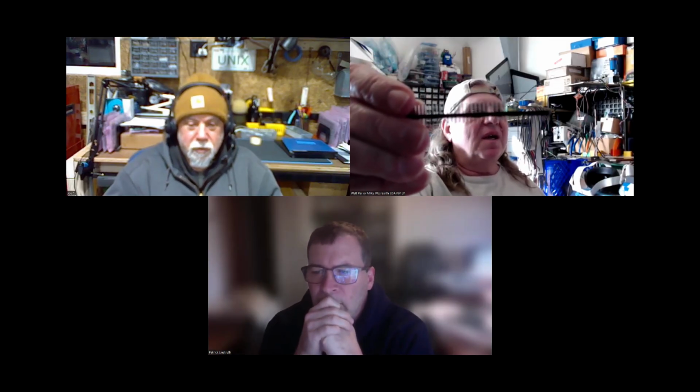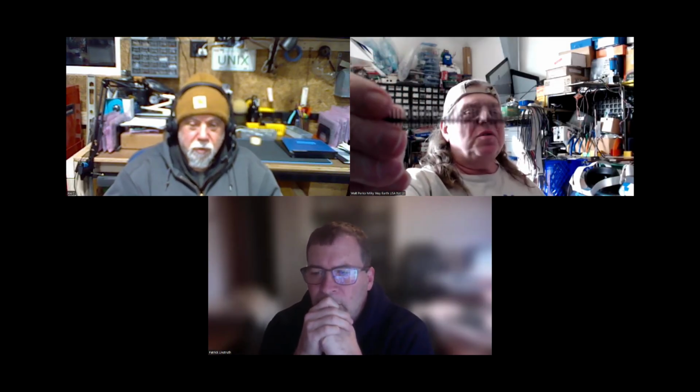I just want to be able to, like a breadboard, just pull it out and stick it back in. See these male headers? Yeah, just have a big breadboard area, and for one project, you just put the male headers in. You just break them off to the length you need, put them in the board, and make your project.